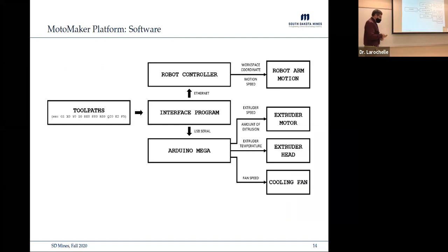So we'll talk a little bit about how we were able to get all this working together. We'll start with tool paths. If you're familiar with CNC G-code, there's G-code right there for you. What our software produced was G-code, which we then transferred into the Yaskawa Motoman XRC controller to translate into robot joint motions in order to realize those.